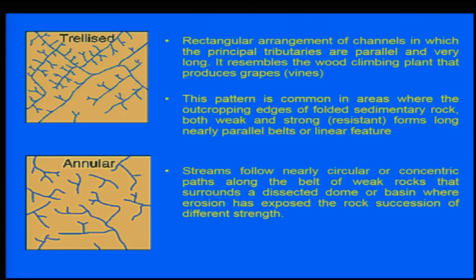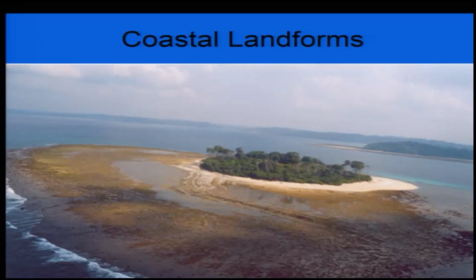Now, all this understanding of drainage network or drainage pattern or channel pattern you can use to interpret the subsurface, and if there is a sudden change in the drainage pattern or a sudden change in the channel pattern, one can interpret it in terms of tectonic deformation, or it could be related to climatic change also. So, one has to be careful while talking about this.